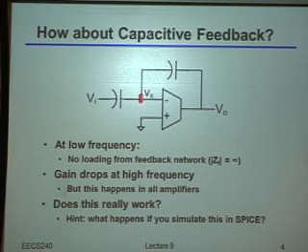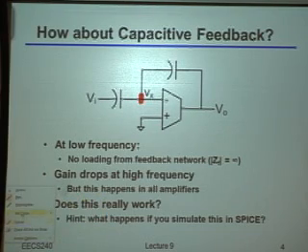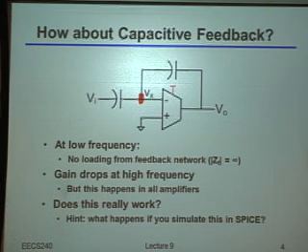Yeah, exactly. So basically the problem is if there's no DC impedance there, you have absolutely no clue what that voltage is at DC. Okay? So just as an example, let's say that I was working in a 1 volt power supply technology. And for whatever weird reason, some particles from space happen to land on your chip, which by the way is totally possible. Or there's just some small leakage from one wire to the other through some hole in the oxide, or pretty much any one of a billion other things.